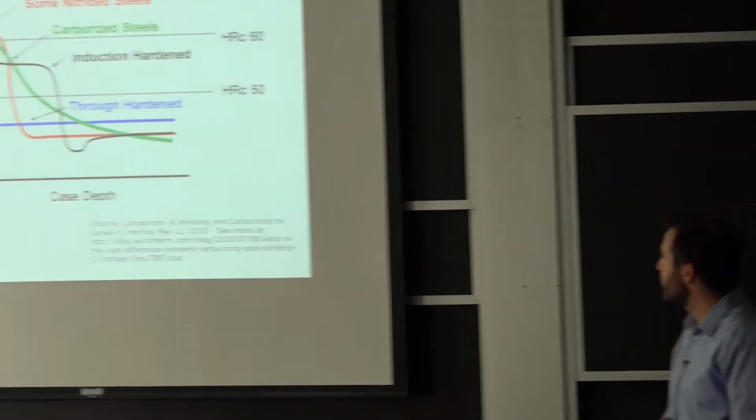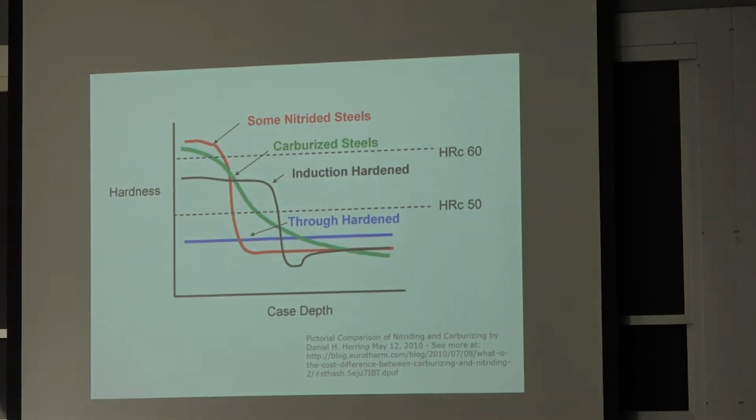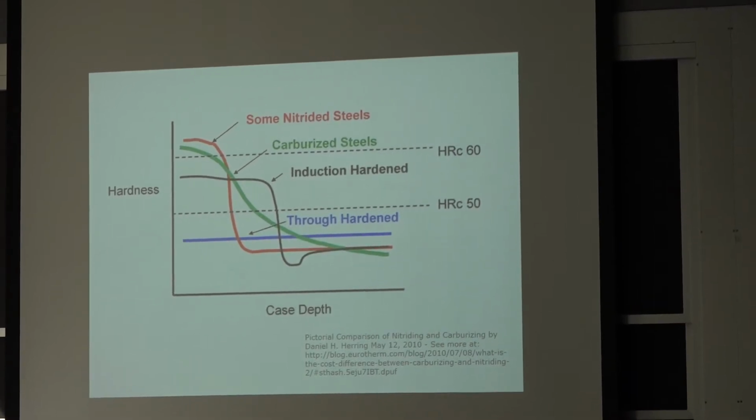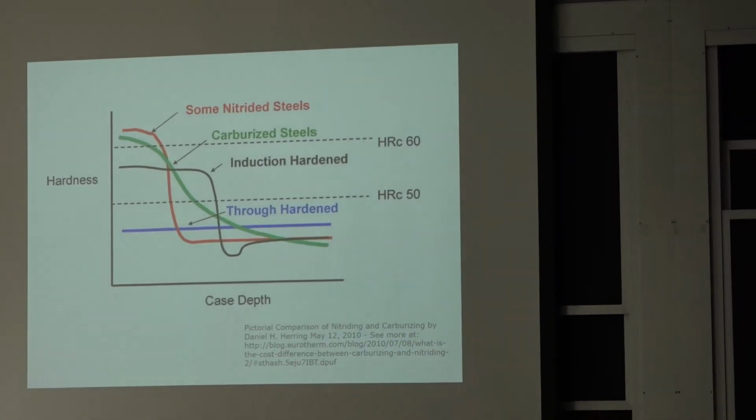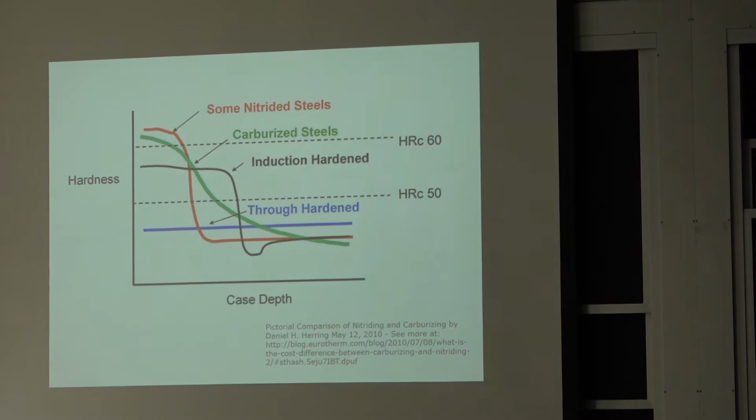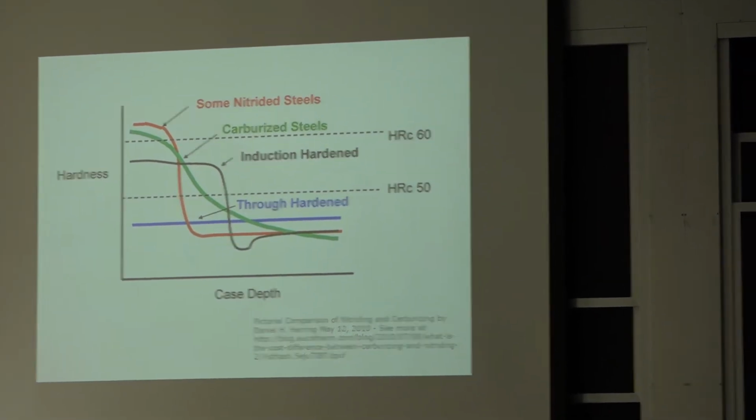Okay, so now we're into completely new material. It's important to think about high-strength steel, let's say for a wear application, so gears and bearings and things that need surface hardness. When I brought the axle of the railroad, I didn't bring it back again today, but you have a surface treatment because you don't want that component to wear on the surface, and then you don't want the entire section to be that hard because it's going to be brittle.